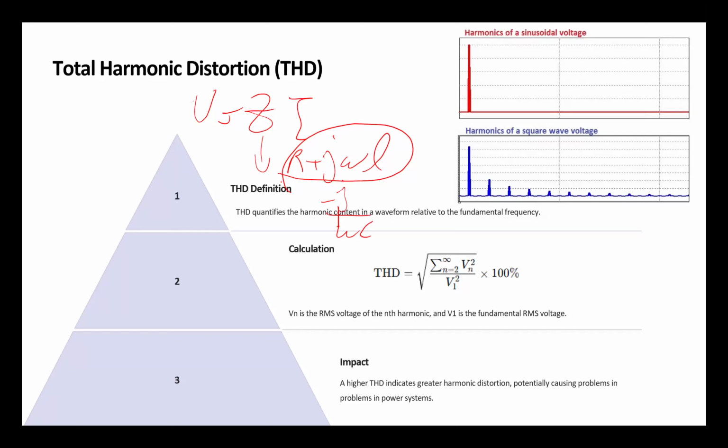The fundamental. Those factors affect the harmonics, but they also affect the fundamental. So to save ourselves from the cost of deviating from the fundamental, we incorporate the fundamental into our harmonic distortion quantity. We make sure we do not mitigate harmonics at the cost of losing our fundamental.